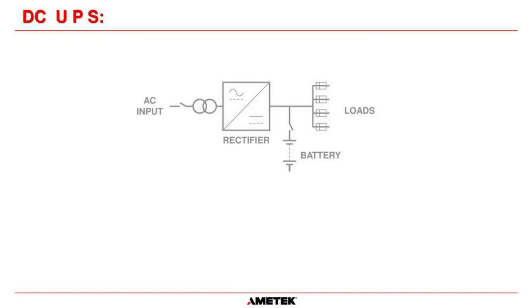The definition of a rectifier is something that changes AC into DC. Okay. So a rectifier takes the AC input, usually from your MCC. So there's your AC input there. And then most chargers are going to have an isolation transformer that you can see on the screen there. And then that goes into a rectifier bridge.